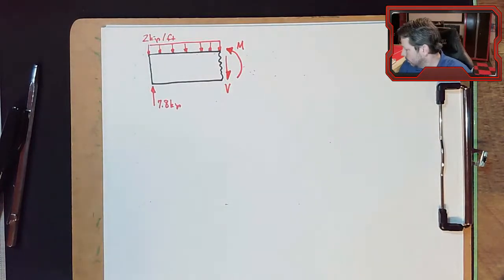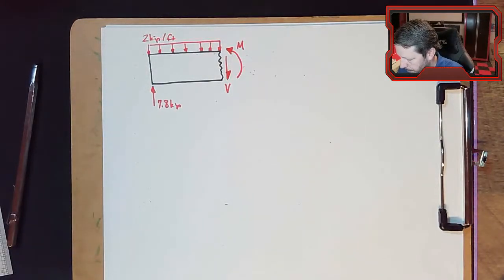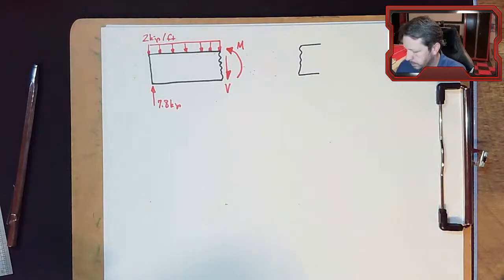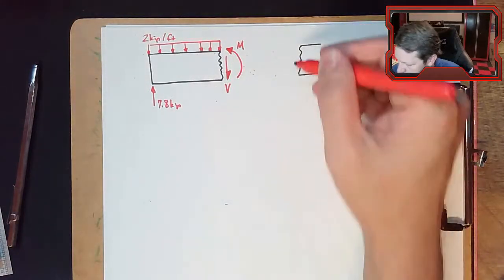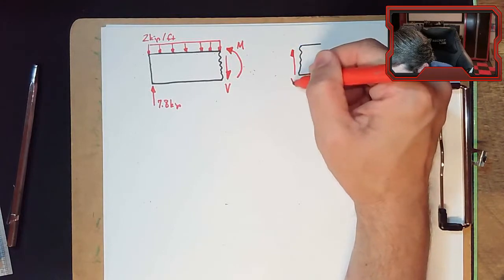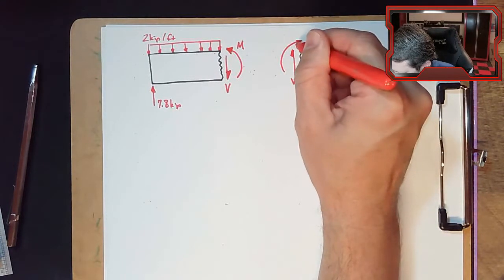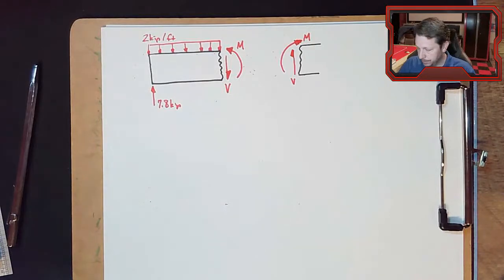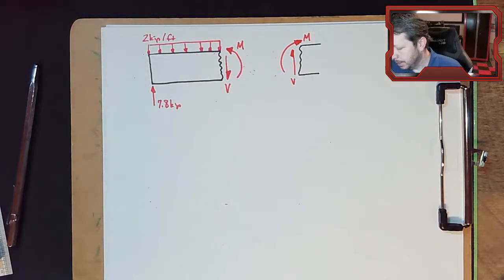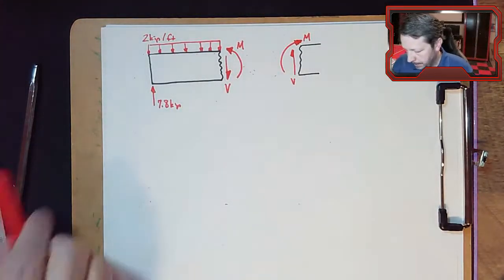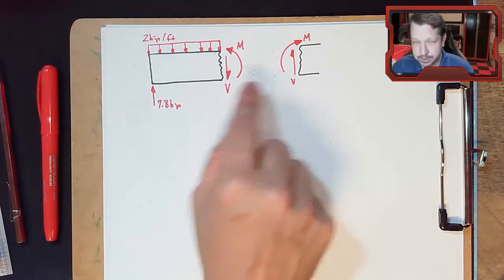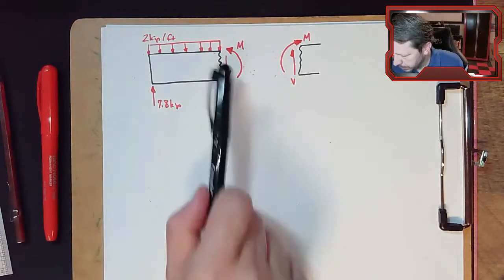And just so you, for total completeness, if you were to draw the other side, I'm not going to draw the whole thing, but if you were to draw the other side of the thing, on this side, you would put the shear force positive if it goes up, and the bending moment positive if it's clockwise. So these conventions you have to follow for stuff to work out later on. When we're drawing the pictures of the bending moment and the shear force in the beam, we need these conventions in place. So that's kind of one of the few times that I'll specify you must draw the free body diagram with these directions as positive. All right, so we're using this half. We don't really need that half.